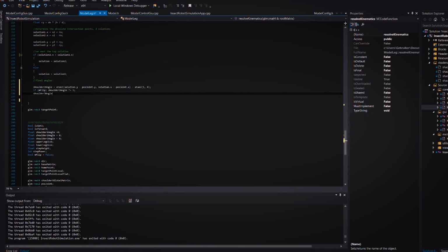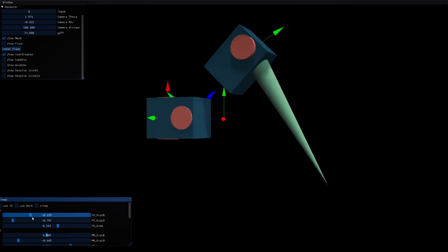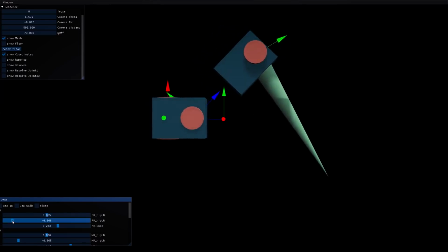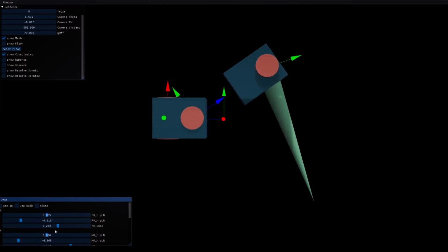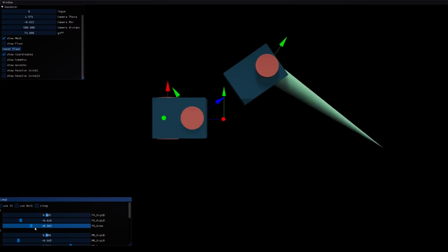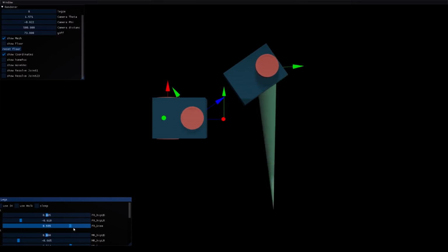I didn't really know how a hexapod would work, and in cases like that, I like to start with making a simulation. The only thing you can control with a real robot are the rotations of the motors. So I started to make a forward kinematics computer model that has that exact behavior. And with that, I could try to figure things out and start testing.